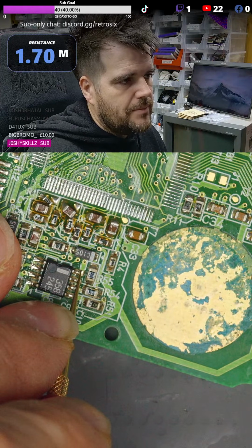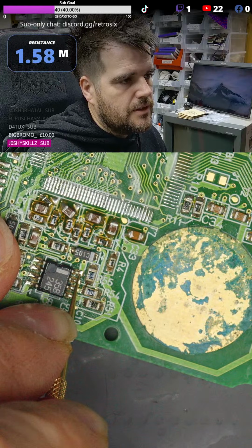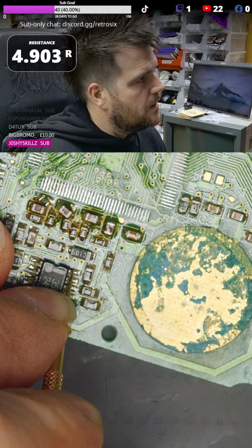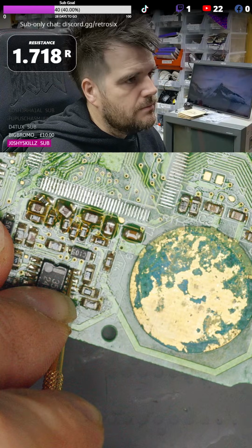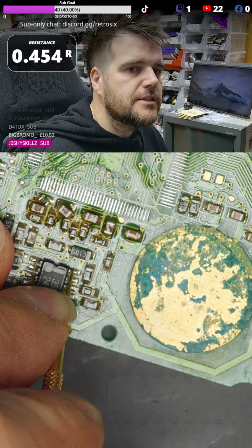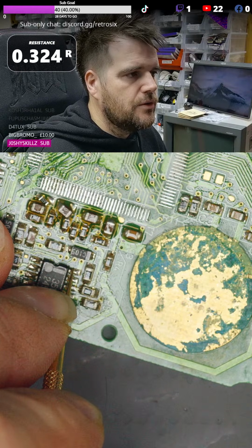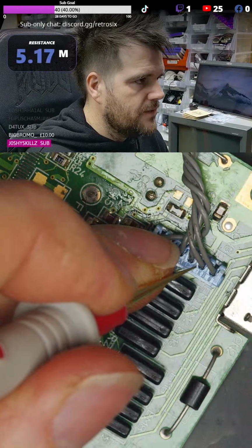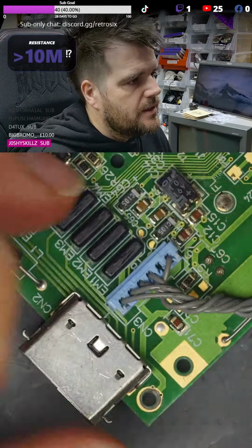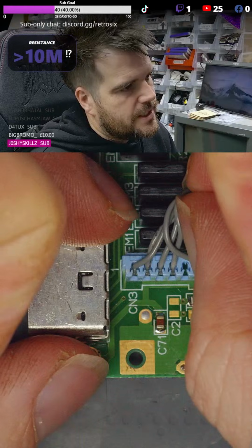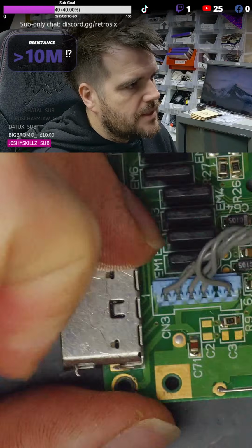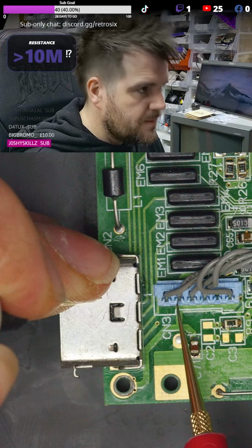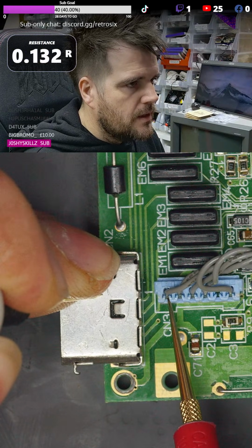So this op amp here is receiving, you probe on it correctly, you know, like 1 ohm, 2 ohm. It's low, but not super low. There you go, 0.4. But if we get right over the short, which is, I believe, this wire here, or effectively this trace here, so this pin, we can probe in even from this side if we suspected. And you see there, the 0.1.